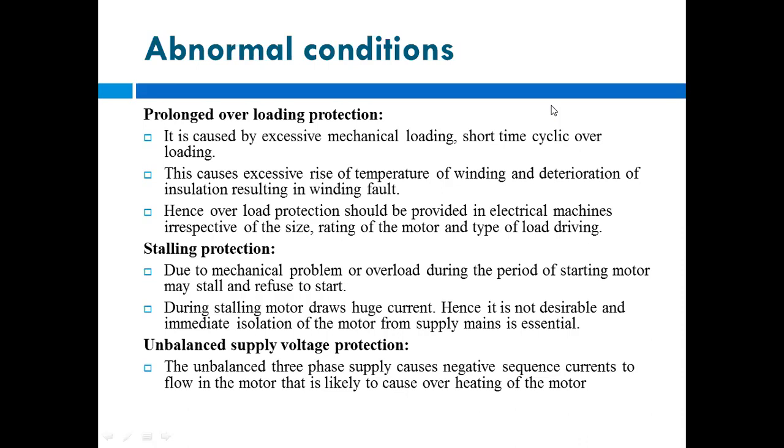So overload protection should be provided in electrical machines irrespective of the size, rating of the motor and type of the load driving. If any type of motor you are using, we have to protect that motor. So we are using relays for this motor protection. Again, there is a differential relay protection scheme for this induction motor protection also.